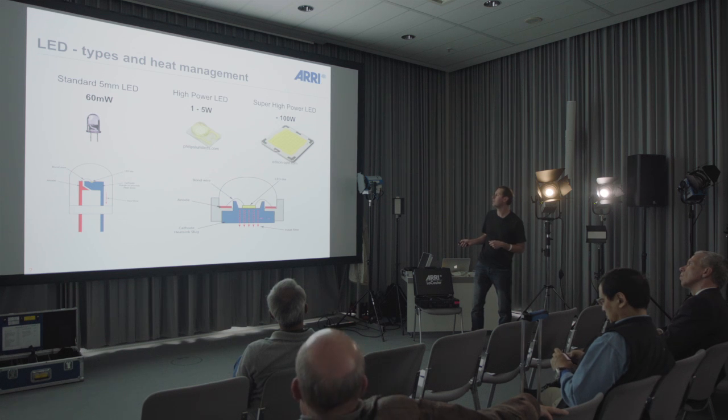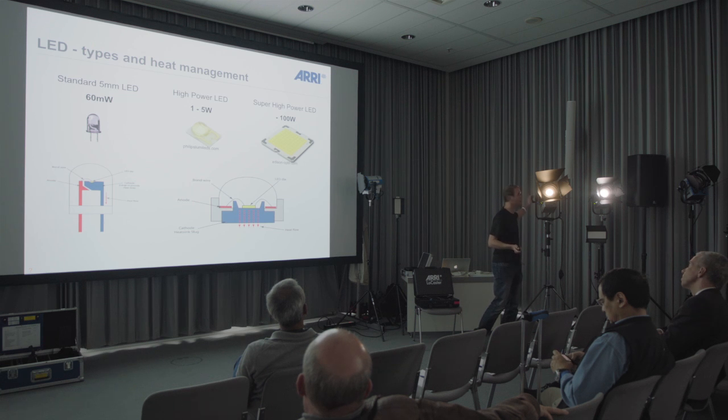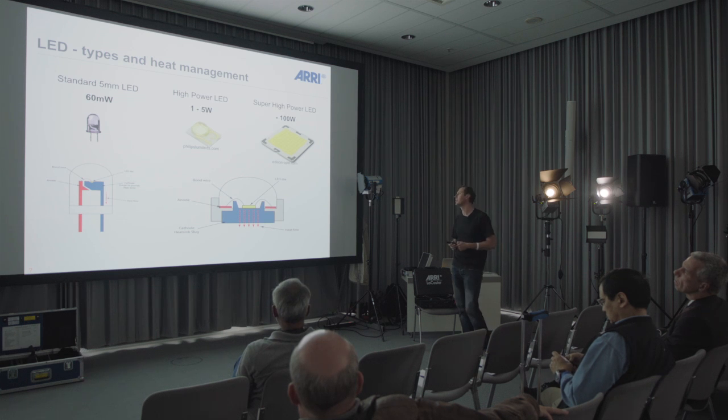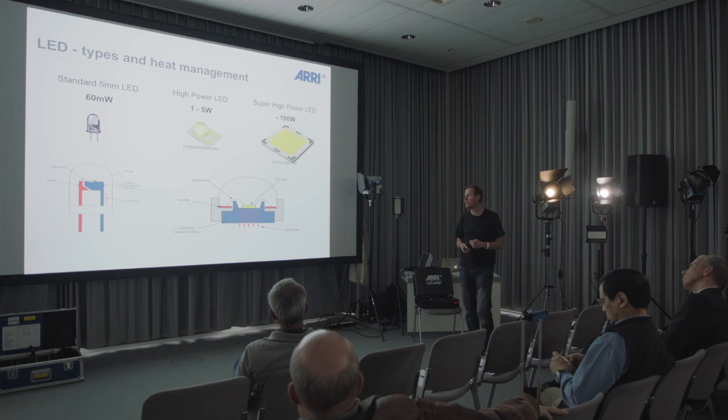So all the LEDs that we use are connected to a bigger heatsink, or we have, like I told you, a fan-cooled system to get the LEDs cooled down. If we don't care for that, if the LEDs get too hot, they don't explode or something like this, but they will get dimmer and dimmer, and they will lose their efficiency. And if you keep the unit running for half a year or 1 year, you will be surprised where all your bright LEDs are gone.